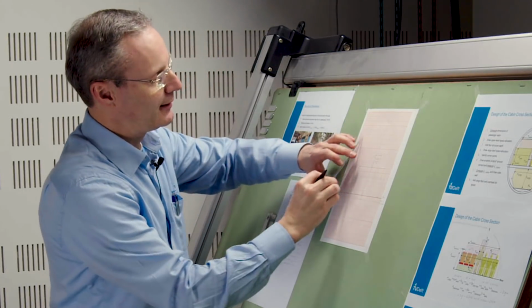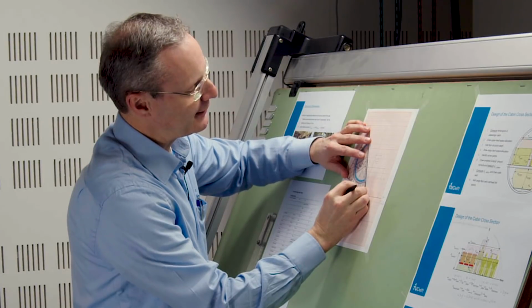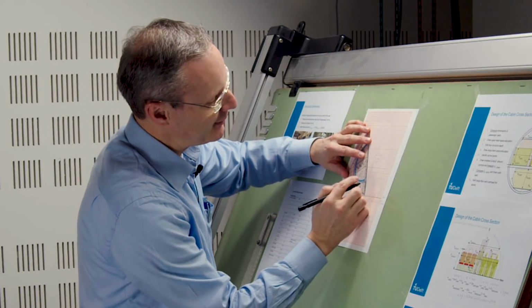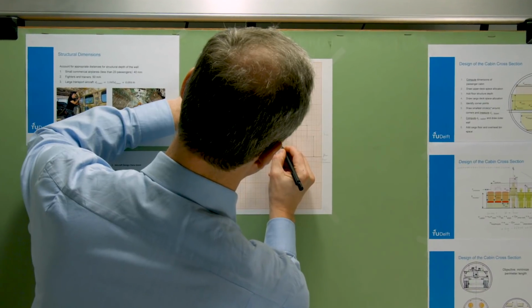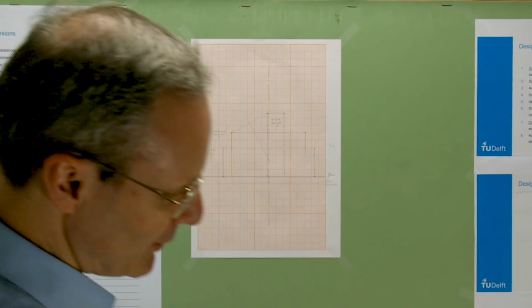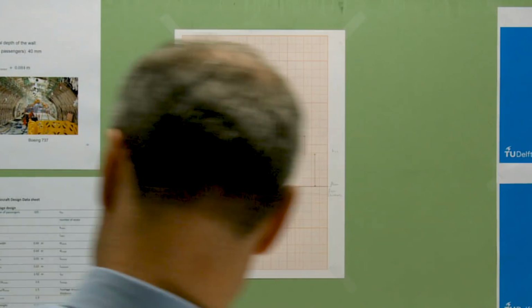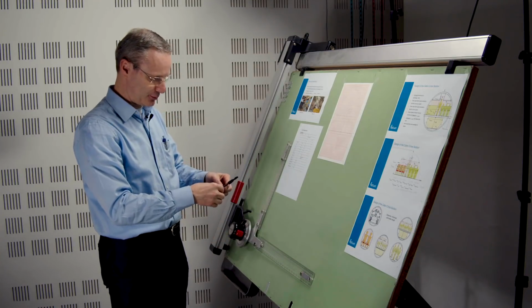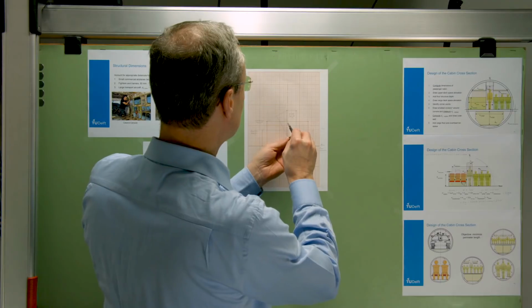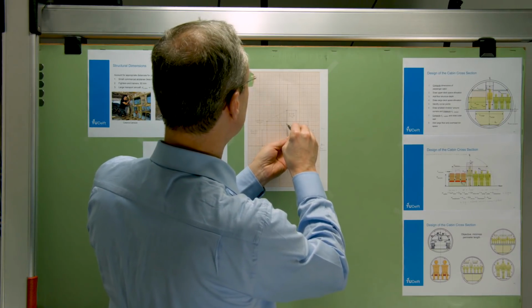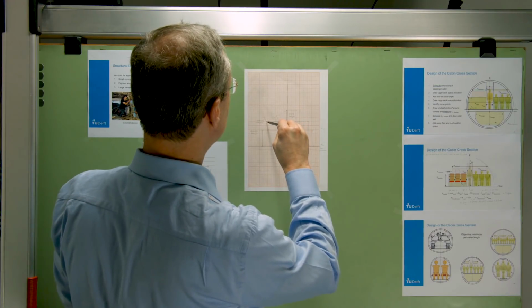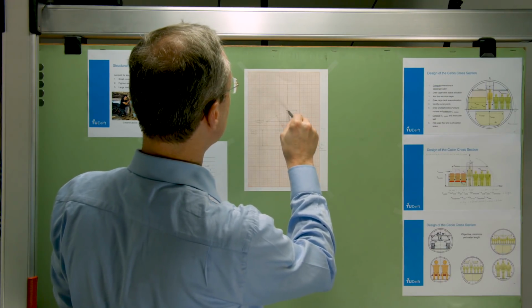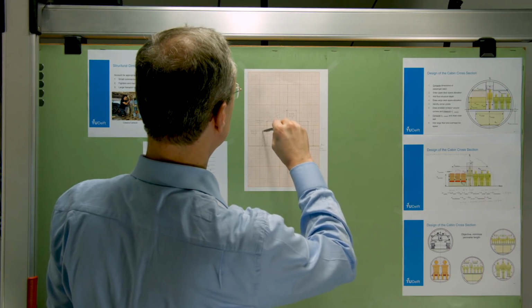And from that point, I'm going to draw a perpendicular line, again with the help of this device, until I touch the center line of the fuselage. And then I find this point over here. And that will be the center of the circle that will touch both points. So I'll put the sharp point over here. I'll measure it such that I have 1 point, and I will see that automatically I have this point as well. And then I draw my circle.